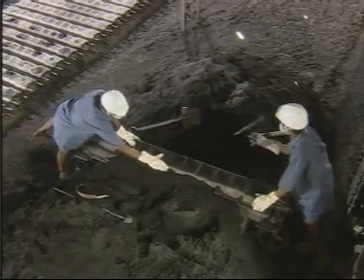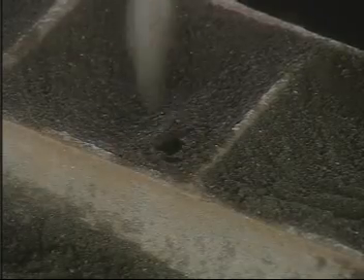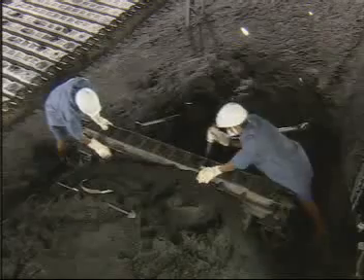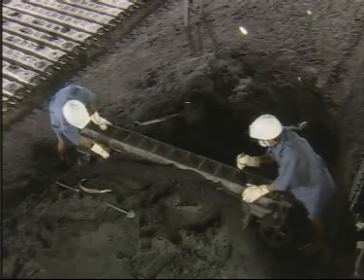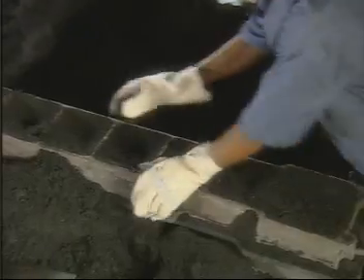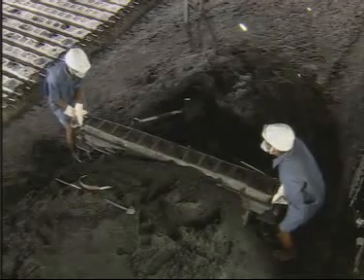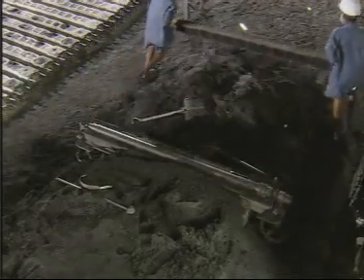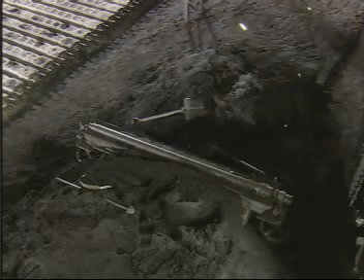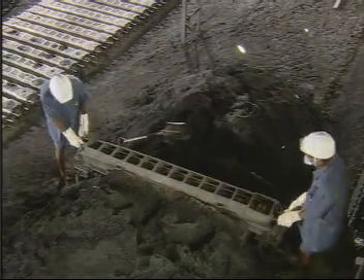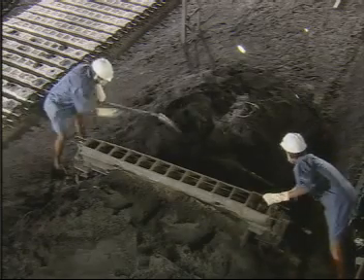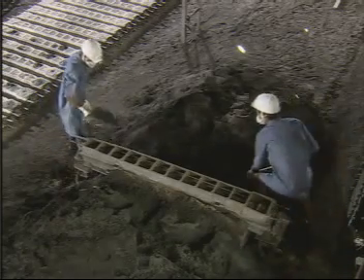A circular bar is used to create pouring sprues at 3 points in the cope for the metal to flow into the mold cavity. The cope box is now carefully removed from the pattern and kept over the loose sand. The bottom half or the drag is prepared in the same manner.